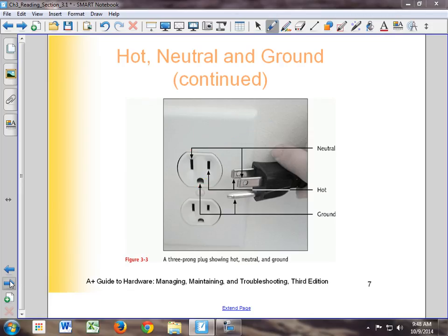Okay, we've got our electrical outlets. And electrical outlets, if wired correctly, which you cannot assume ever on any house unless you do the wiring yourself and been inside the wiring, this is the way it's supposed to be wired. The big prong is supposed to be neutral. You could stick a fork in it and you would not get hurt. Theoretically, I would not do it, because if you didn't wire the house, you don't know that it's neutral.